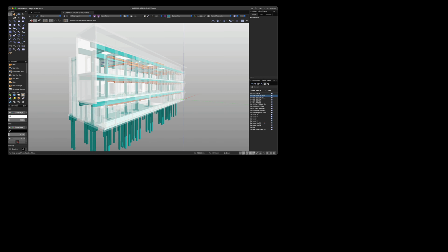The process will require an exchange of IFC files from all involved in the design of the project. You should always combine the IFC files with your Vectorworks model. This will give you a chance to visualize coordination issues directly in your design environment and allow you to make the appropriate changes to resolve issues.